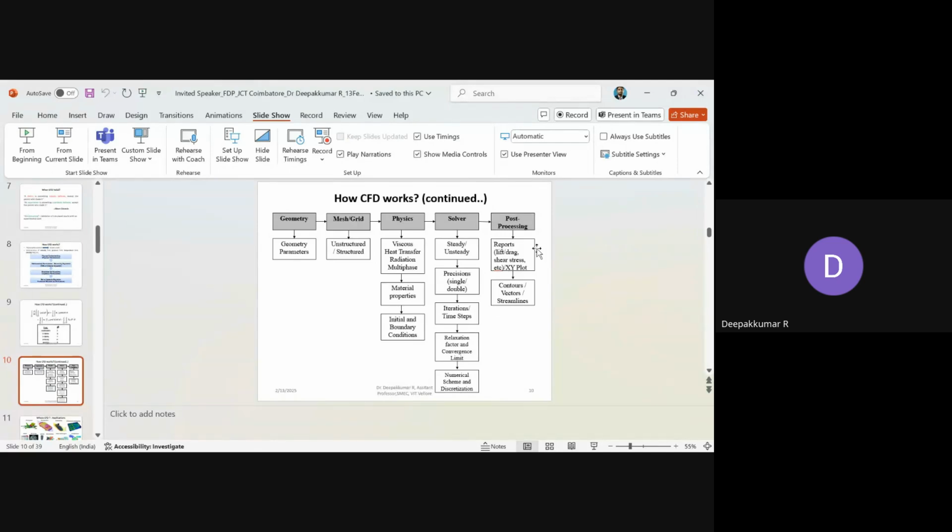Say, for example, chemical reaction in combustion. In addition, many components like species, what species are involved in the combustion, that data will also come, and the data will be stored at each and every grid point. The data we then process for engineering parameters like drag, lift, pressure drop, and Nusselt number. These are derived from the raw data: pressure, velocity, temperature. These are the field data variables.